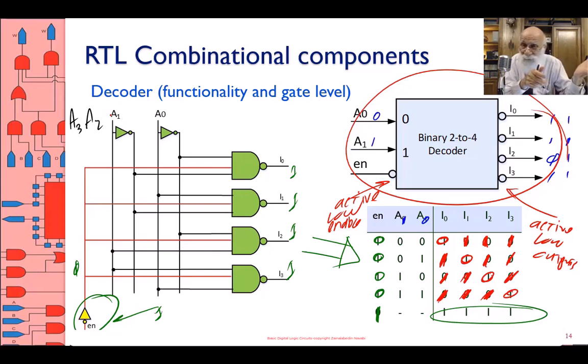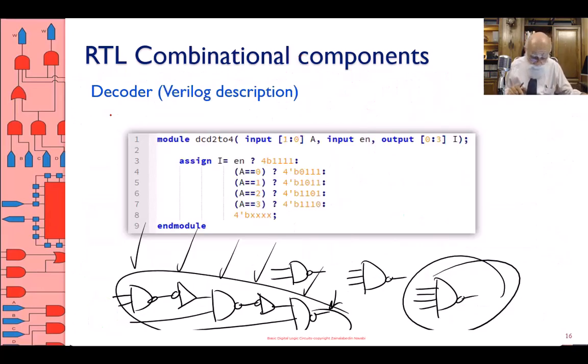Sometimes you have no choice. Sometimes the only gate you have is a 2-input NAND gate, so live with it. Cascade if needed. Sometimes the only decoder you have is a 4 to 16 decoder, and then if you need larger decoders, you have to take this 4 to 16 decoder and build larger ones by cascading. So this is explained: cascading adds delay, both in ANDing and also in decoding.